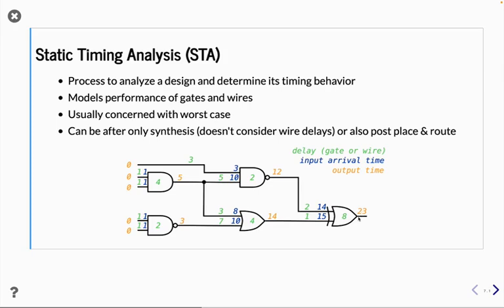Well, in green, we have the various delays. Okay, so this XOR gate takes 8 time units, which is longer than 4 for an OR and 2 for an AND. There are some amount of time delays for these wires. Maybe they're longer or shorter, or more circuitous paths. And so you kind of see what's happening, right? For example, the blue is the input arrival time, and the orange is the output arrival time. So you see, for example, that originally all these inputs are available at time 0, perhaps on a new clock cycle when things are changing.